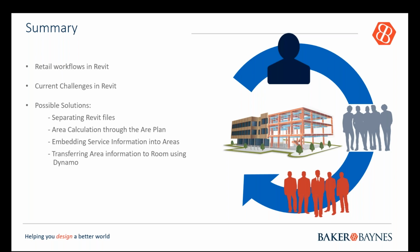We also highlighted that there was a problem when consultants used the architect's file, because now all of our information for tenants is sitting in the area plan, and that's very separate from the room information or the floor information. So we looked at using Dynamo to help automate the transfer of information from the area plan into the room or the floor plan. So we've done that as well.